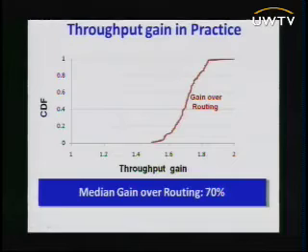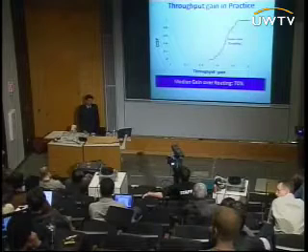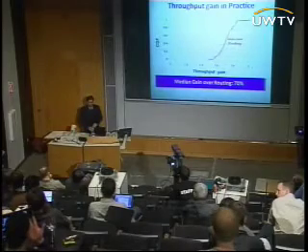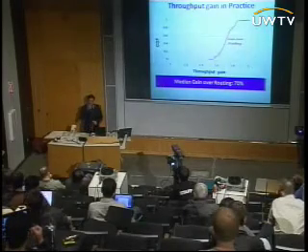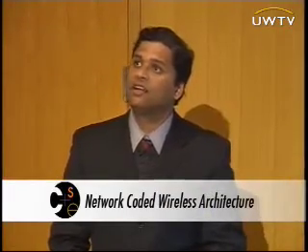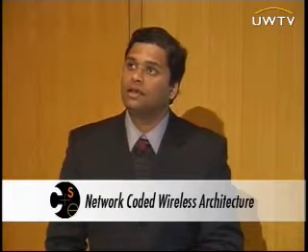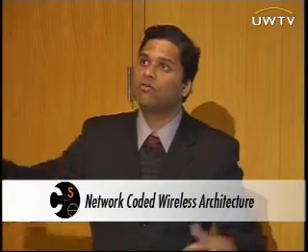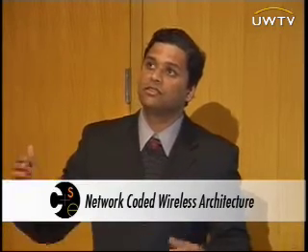Yes? So for this protocol, can you only have two senders? Can you have multiple senders, but everybody has to hear all but one? What's the rules on what you can do? So you can have more than two, but it gets very hard to scale it after 3 or 4 packets. The reason is just the way these things interfere and what is the dynamic range of the ADC itself on these radios. If you have many signals interfering, it's very hard to distinguish these different signals.